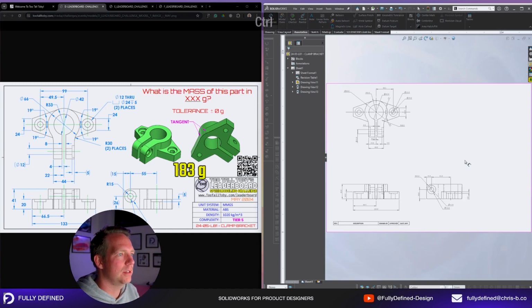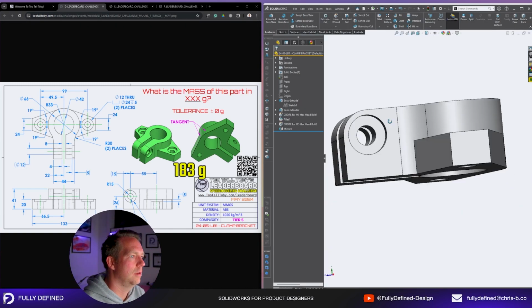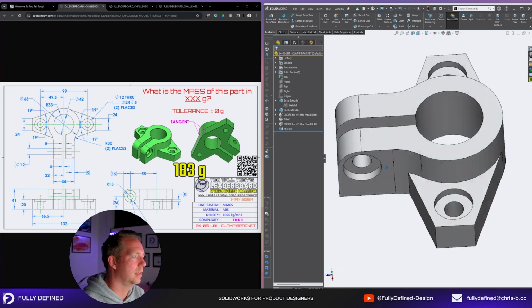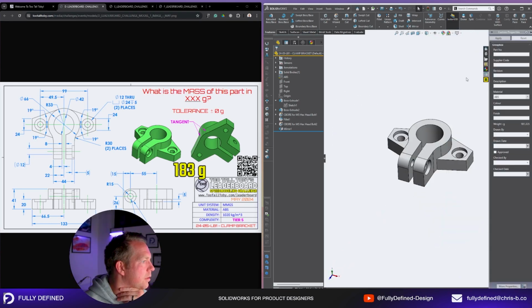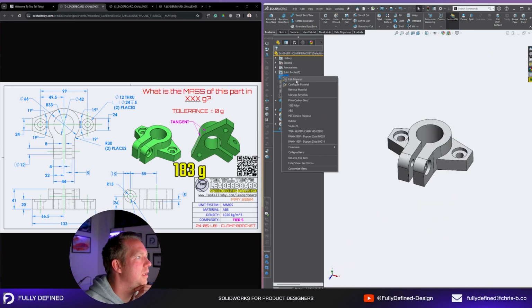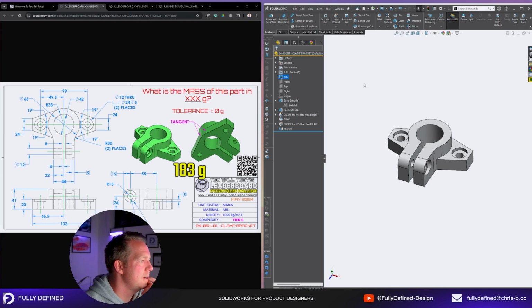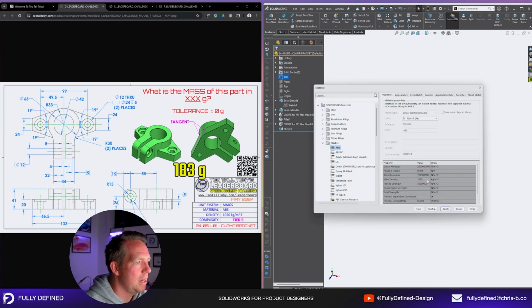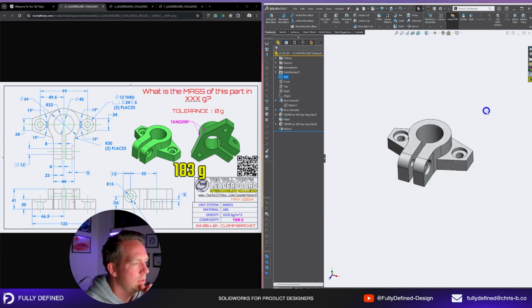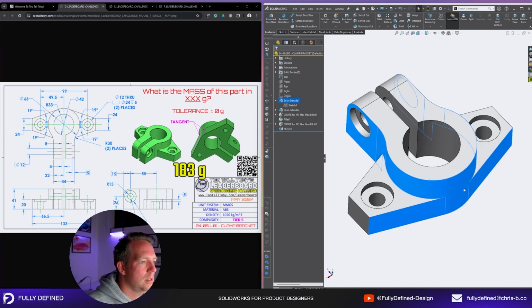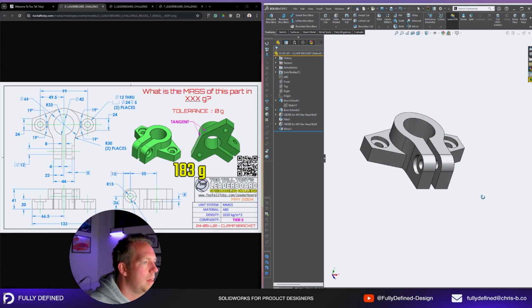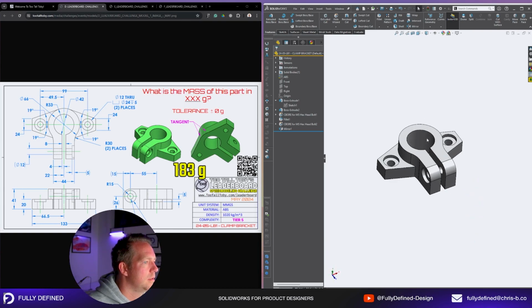So let's save this drawing too, just for reference. Now we want to make sure all our geometry is correct, like the holes all the way through. Material is right, ABS. Check the density is right. So I'm just going through and trying to eliminate issues. So density is correct, of course. Are these edges tangent? Yes. All right, so maybe there's a tricky element somewhere.